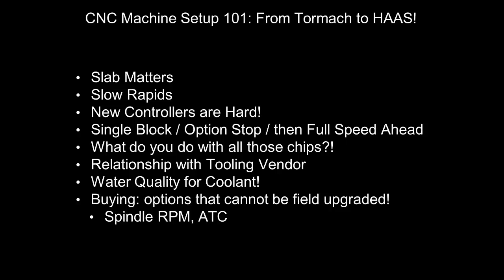So maybe I should jump in, because I don't think you can overstress this enough. The bulk of your crashes, and if anybody wants to jump in on this in the chat, go ahead, are going to happen where there's operator error. That operator error is going to happen when you didn't pick up your work offset right, you didn't pick up a tool right, you have the wrong tool in the carousel, these operator error things. So what John is showing is that by single blocking at the beginning, you have a chance to validate that you're coming down to the right height before just ramping down in.